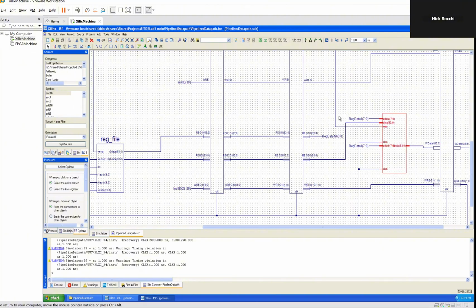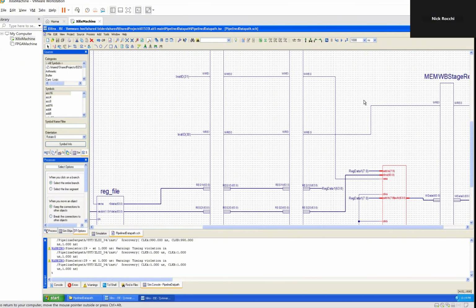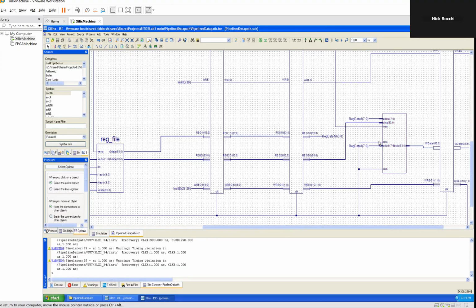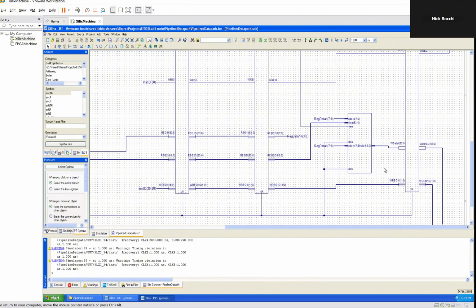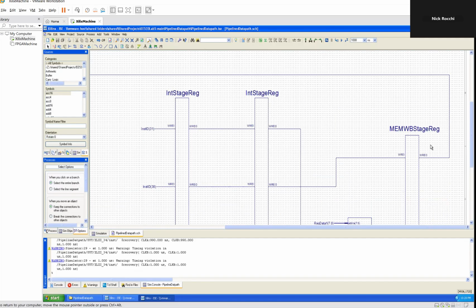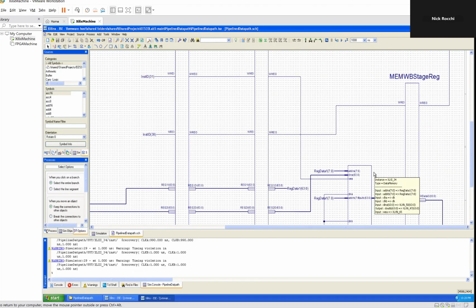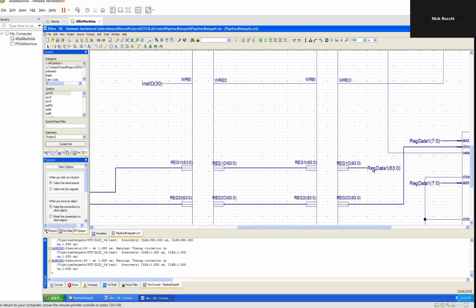We use our write enable that we get in our ID stage, and our address, or our data that we get from our register file, in order to access or write data from the data memory block. We then pass our write register, our write data, and our write enable back into the register file if we need to.